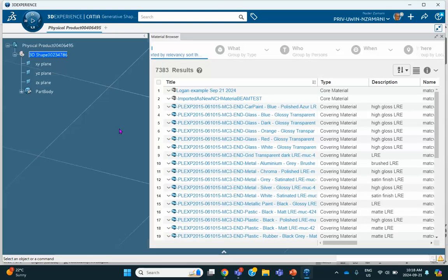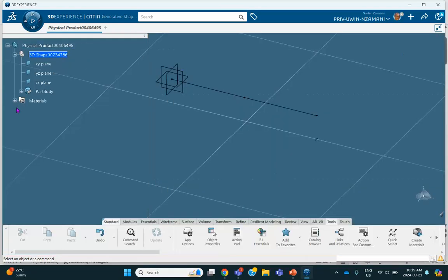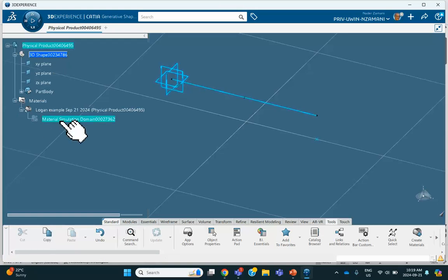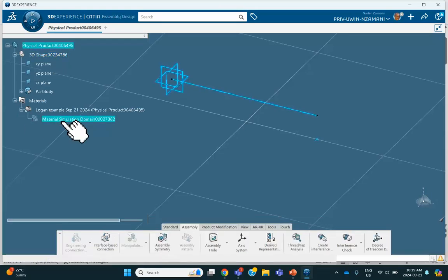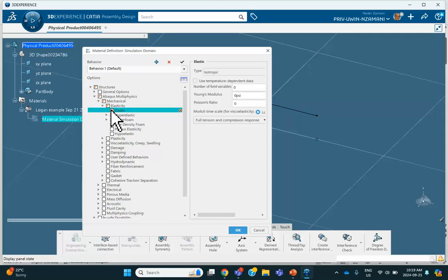Okay. There we are. Let's take this thing, put it on that. I'm going to close that and just put in our numbers there. Okay. So it is a structural, Abaqus multiphysics, mechanical, elasticity, elastic, and it says 210 gigapascal, 210 GPa. It's going to convert it to PSI because my units are on PSI default units right now. And Poisson ratio is 0.3. Okay, good. That's pretty much it. Let me do a quick save here.